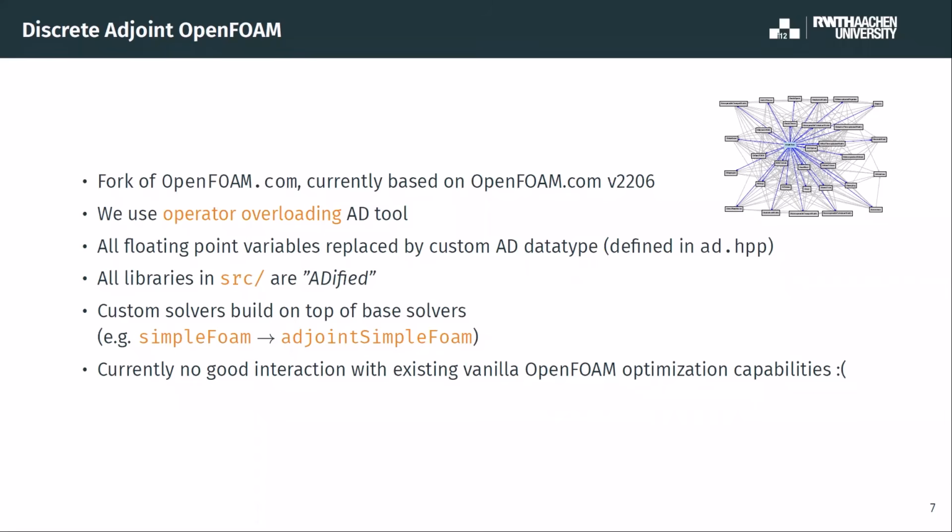And then for the solvers, we selectively treated just a few, but most of the important ones still compile. Obviously, if you don't tell it to, they don't do anything meaningful. So stuff like blockMesh, snappyHexMesh, pre- and post-processing, whatever, still works. But we didn't touch every esoteric solver and fix it.